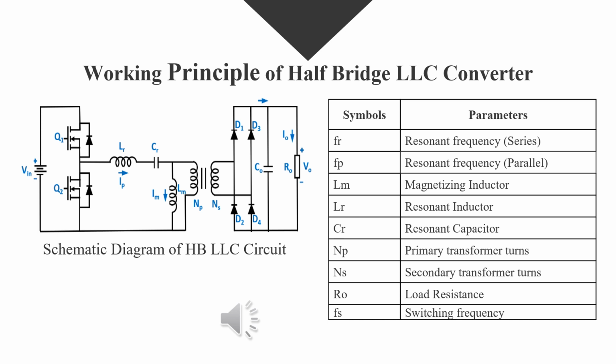The amount of current or associated energy to be circulated and delivered to the load is then mainly dependent upon the value of the resonant circuit's impedance at that frequency for a given load impedance. As the frequency of the square wave generator is varied, the resonant circuit's impedance varies to control that portion of energy delivered to the load.